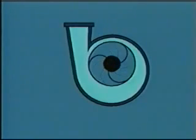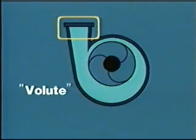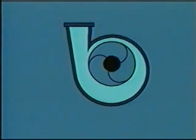It enters a specially designed area of the casing known as the volute. The volute is wider at the discharge nozzle than where the fluid leaves the impeller. There's more space, which causes the fluid to slow down. Its velocity decreases. The fluid gives up some of its energy. But that's not all. Energy just doesn't disappear. It's converted into pressure. And that pressure forces the fluid out of the discharge nozzle. The fluid leaves the pump at a higher pressure than when it enters.